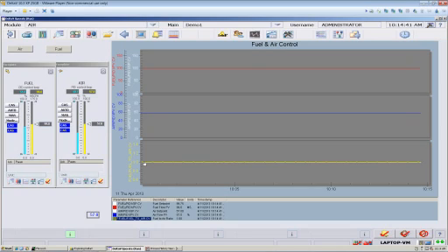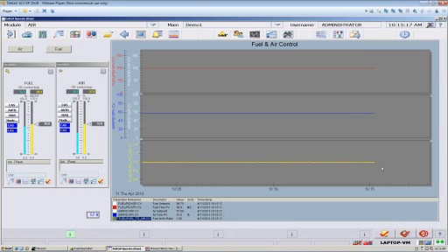No matter what my firing rate is, no matter how things are changing, I want the right amount of air to burn this much fuel. Now, this isn't going to be a boiler control demonstration. It's not a burner demonstration. This is just a good generic example I could find on how to coordinate two different flow loops to work together. This could be two different reactants to your reactor. This could be two ingredients to a baking process. Anytime we have two flow loops, even if they have drastically different inherent dynamics, I want their automatic mode behavior to be well coordinated.